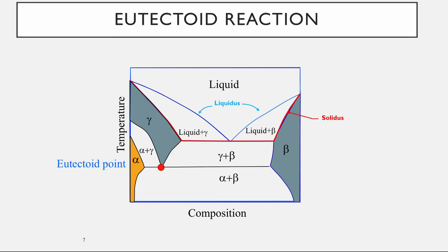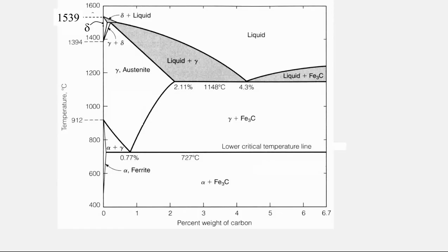And the eutectoid point, we can actually see on our plot, is this lowest point that our gamma could exist before everything transitions to alpha. Just the same, we have a eutectoid composition, so how much beta is left, or material B and material A is in the composition, and it occurs at a set temperature, so we'd have our eutectoid temperature, very much like the eutectic point.